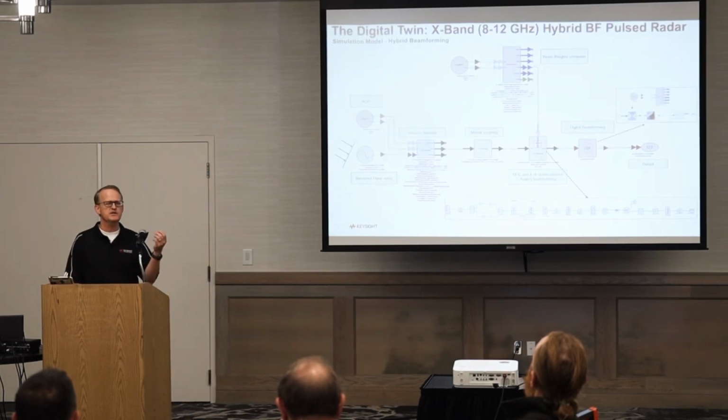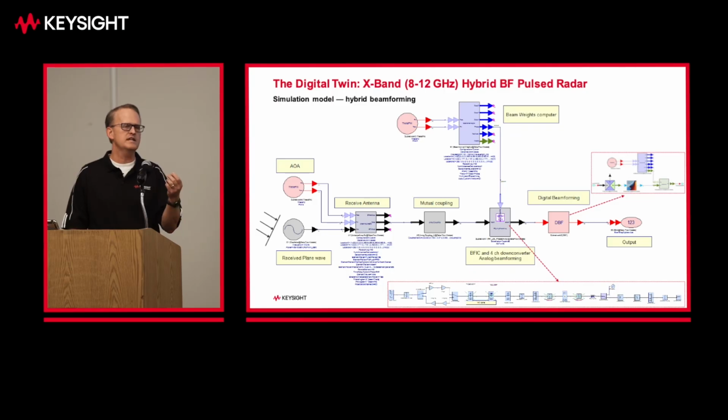So the phase shifter can handle quantization. It can have S parameters for each state of the phase shifter. You can give it a raft of S parameter files from the vendor if it's ADI, or you can measure it yourself, and it'll handle those shifts of the phase shifter with the S parameters. It knows you're at this phase shift state. This is the actual phase delay.